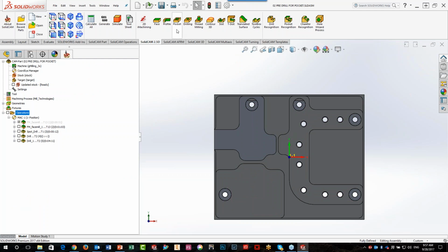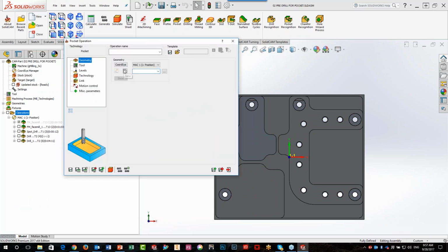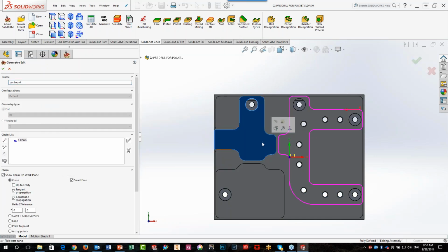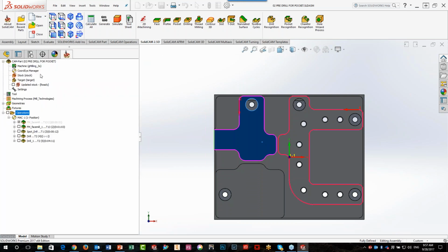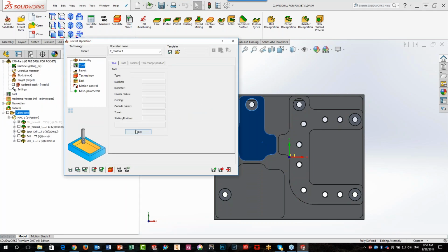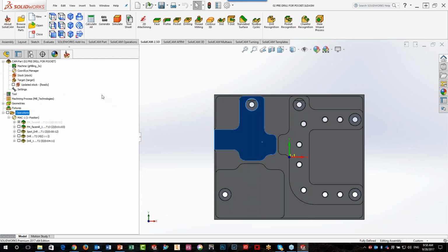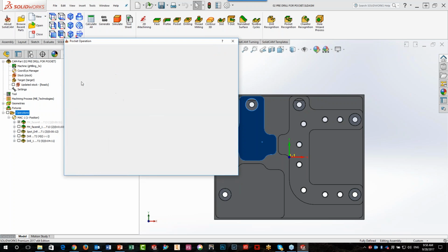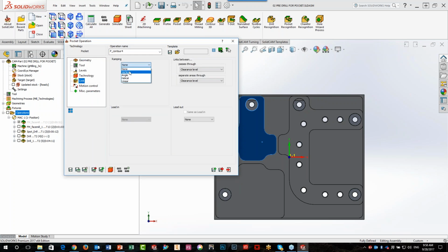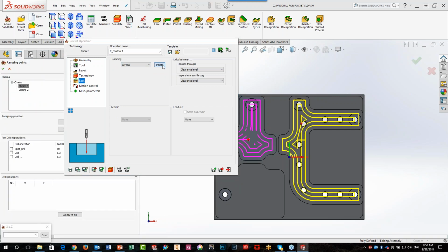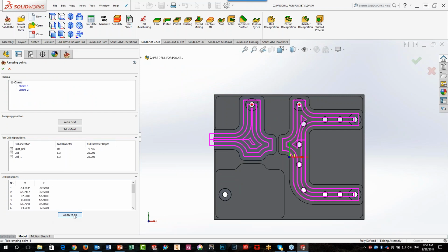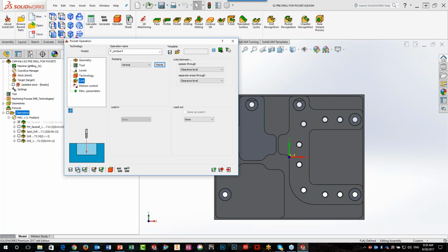We'll do it over here. Pocket. So we can see this with a much better workflow. We have 1, 2, 3. Choose my tool. And I'll be using again my 8 millimeter end mill. Go to my links, my ramping. I'm going to have it at vertical. Let's do vertical points. Go directly to apply to all, and you'll see it'll jump directly to all those holes over there. Except that, let's do just save and calculate.